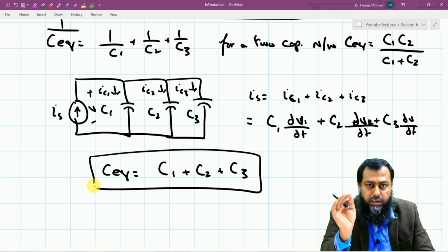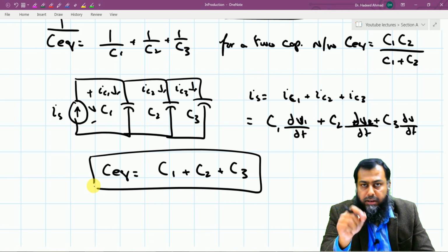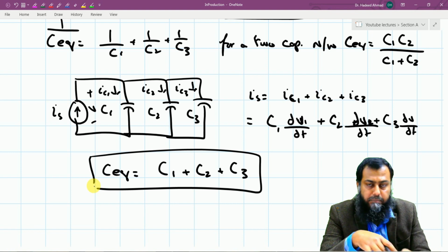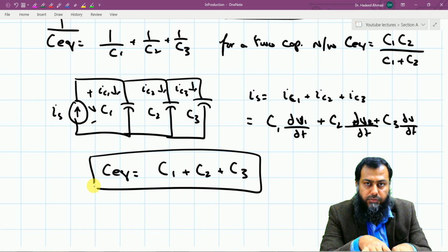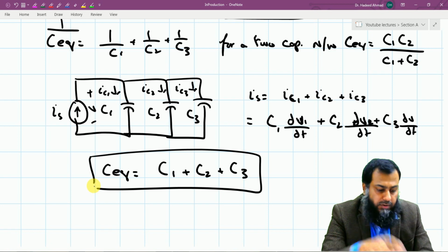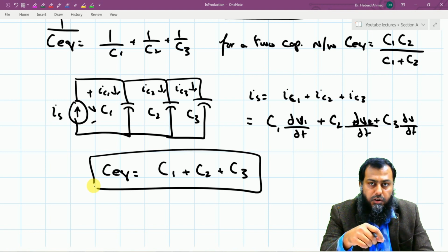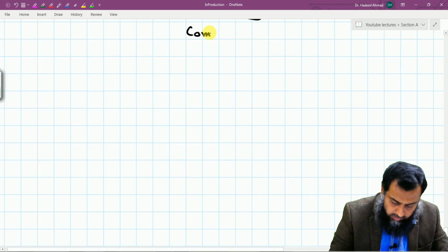We do not have to design the capacitance, just like we discussed that for any given application, the inductor may not be available in a given market, and therefore first the core is purchased, and then based on the designing of that particular application, the shape of the core is selected, and thereafter we wound the coil on that particular core to develop a given inductor. But this is not the case for the capacitors. Capacitors are easily available in the market, and they can be used in the circuit just like a plug and play device.